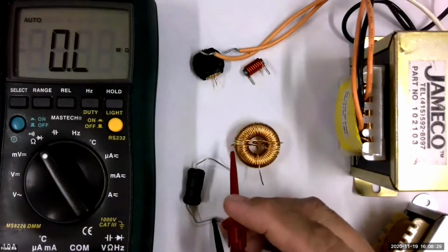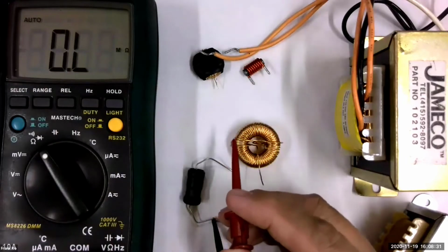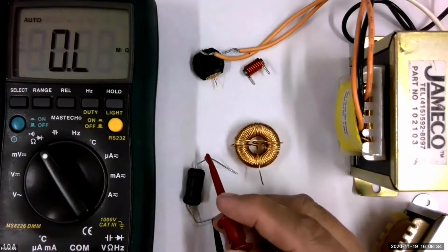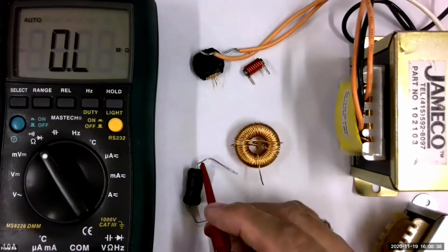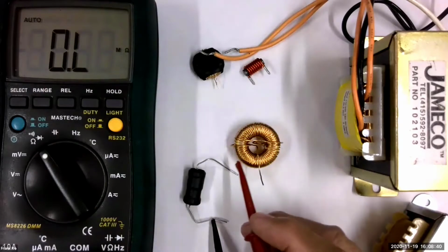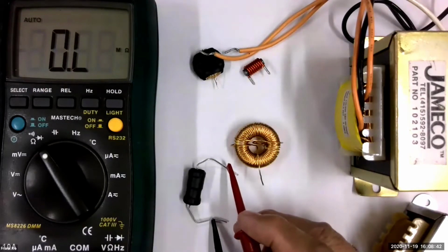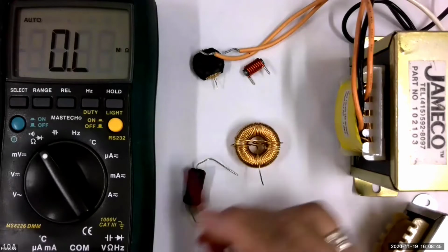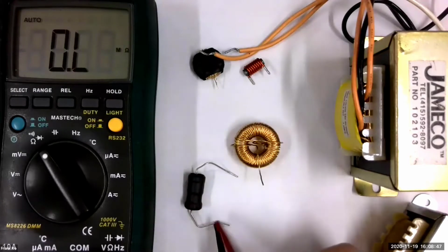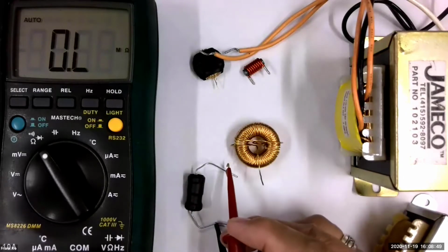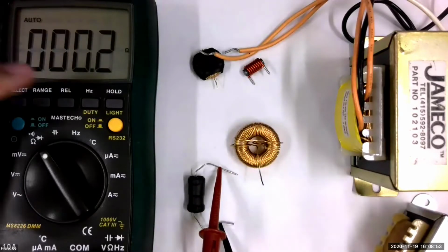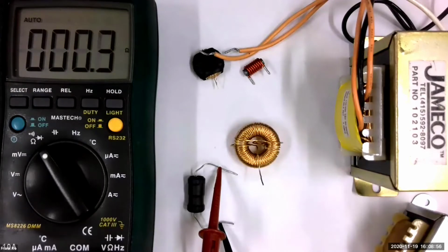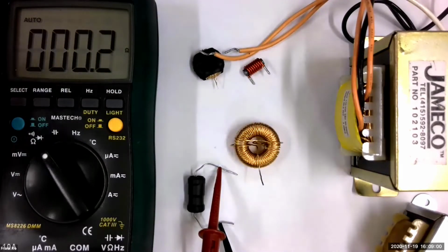There is a slight relationship. Lots of henries doesn't necessarily give us lots of ohms. Lots of henries occurs because we're using lots of wire. But when we go to measure the resistance of this lead, through the coil all the way to the end where it comes out on this side, take a look at how many ohms this works out to be. It's a fraction of an ohm, if even that. Look at that, 0.3 ohms. So we're basically measuring the resistance of wire.